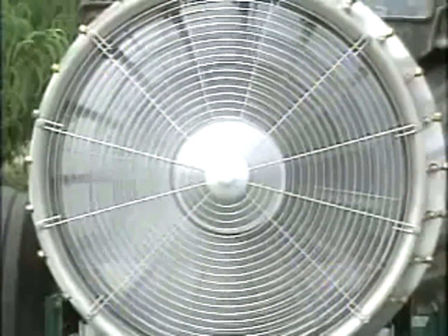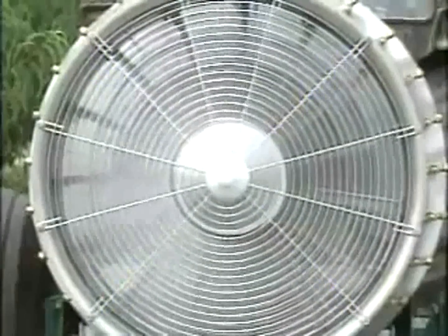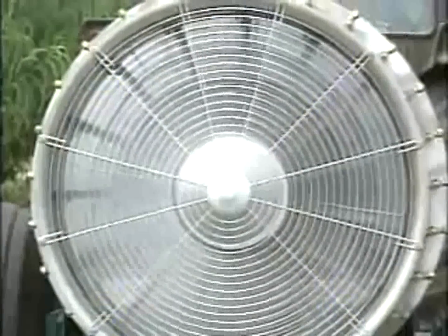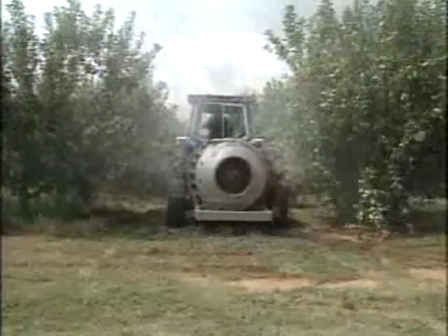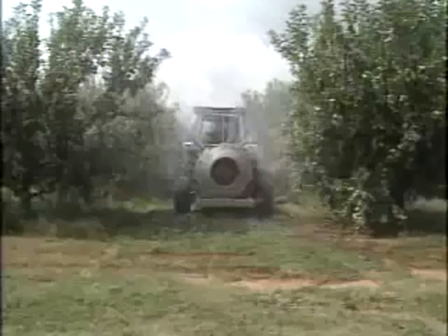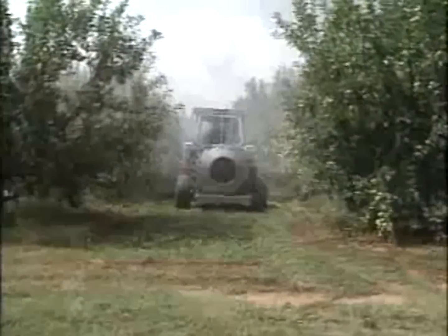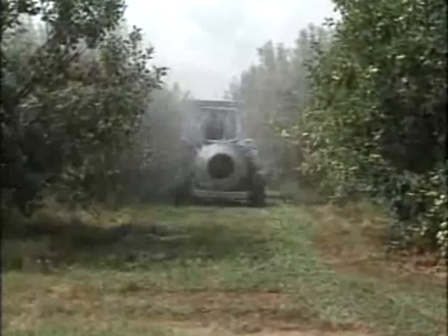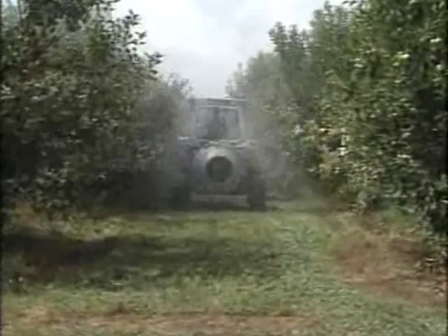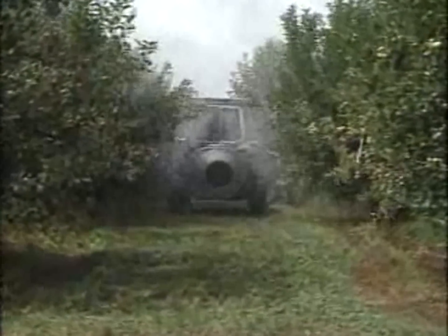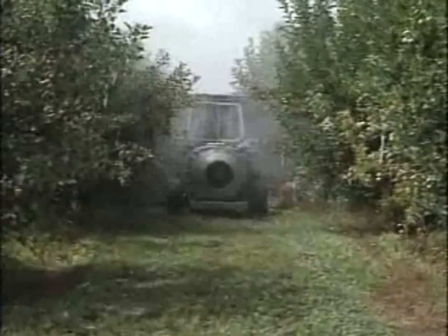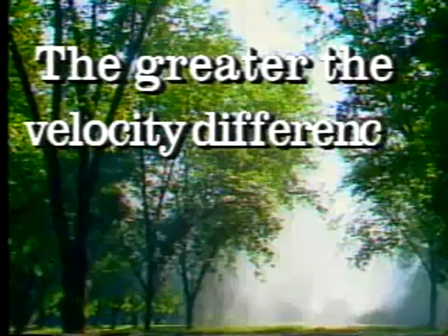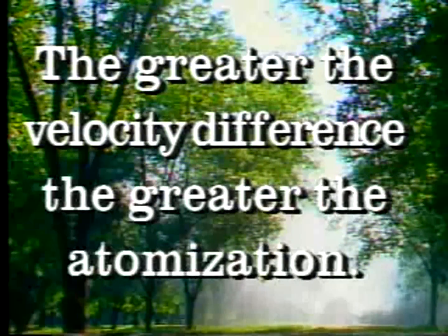There would be no air blast without a fan to create the air stream, so the fan, either axial or centrifugal, is very important. Together, the air stream and the nozzles atomize the liquid from the tank, breaking it up into small droplets. Most sprayers depend on the nozzle for atomization of the spray. The effect of the air stream on spray droplet size is proportional to the velocity difference between the liquid spray and the air stream. The greater the velocity difference, the greater the atomization.